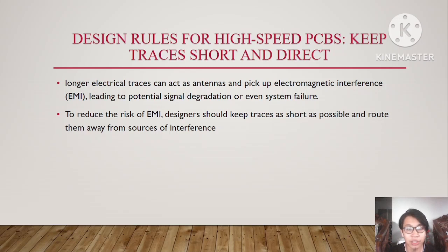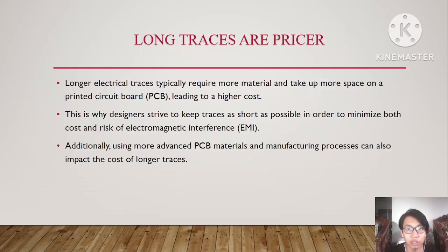To reduce the risk of EMI, designers should keep traces as short as possible and route them away from source of interference. And long traces also are pricier, and longer electrical traces typically require more material and take up more space on a printed circuit board (PCB), leading to a higher cost. This is why designers strive to keep traces as short as possible in order to minimize both cost and risk of electromagnetic interference. Additionally, using more advanced PCB material and manufacturing process can also impact the cost of longer traces.